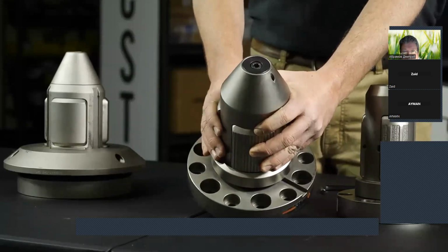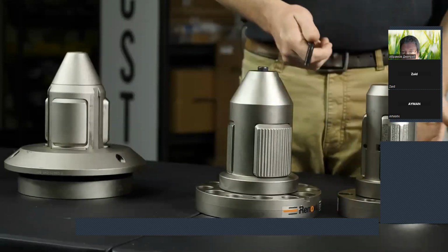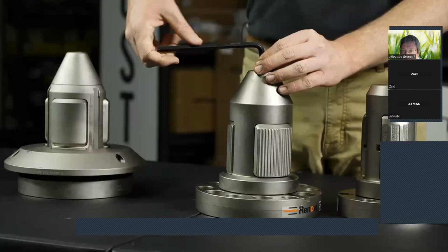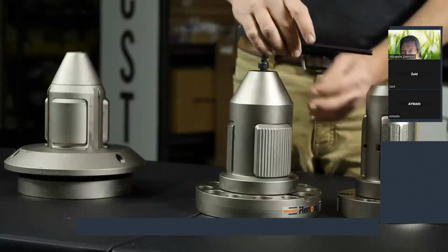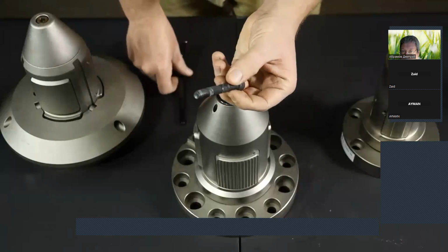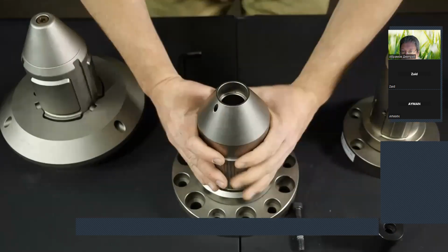Earlier, I spoke of our focus on providing a chuck that is designed to be easy to install. Now, more importantly, let's look at how our chuck is designed for easy use and simplicity of maintenance. We keep your plant maintenance team in mind. 3 components. That's it. As you take our chuck apart, you may notice right away how short our center bolt is. Why is that? Because our flange is made from one piece of forged steel.